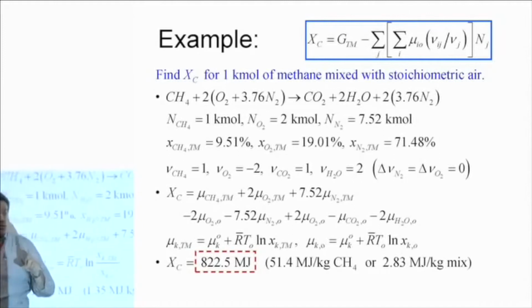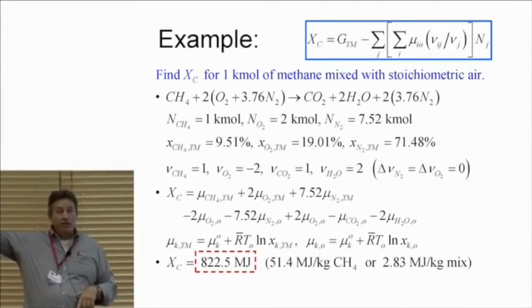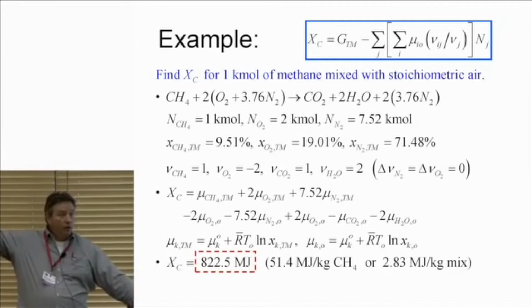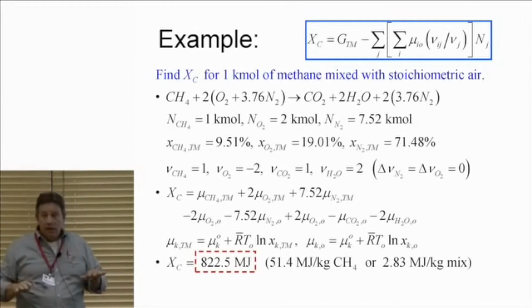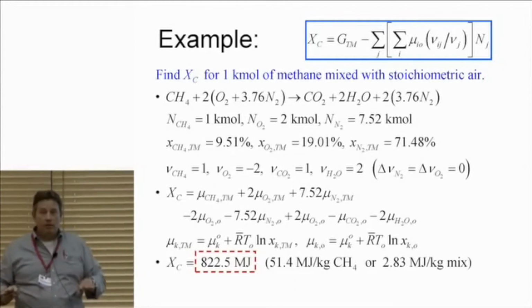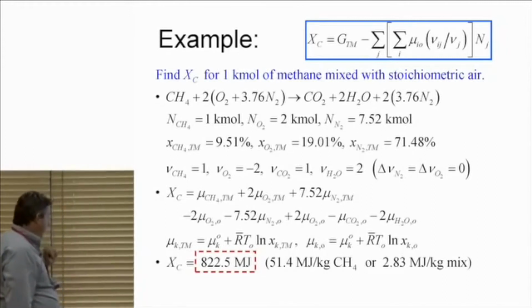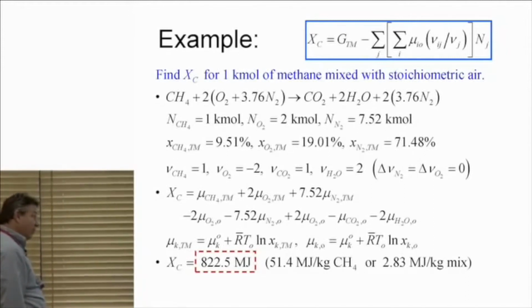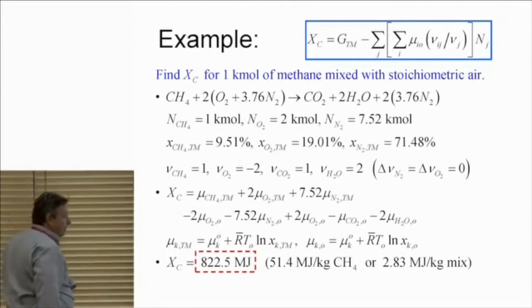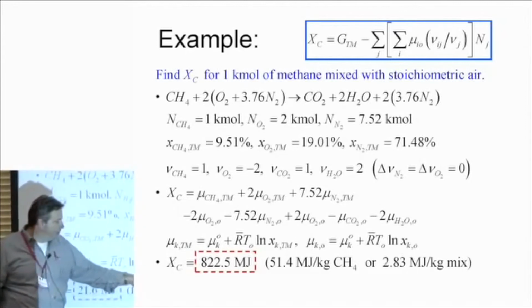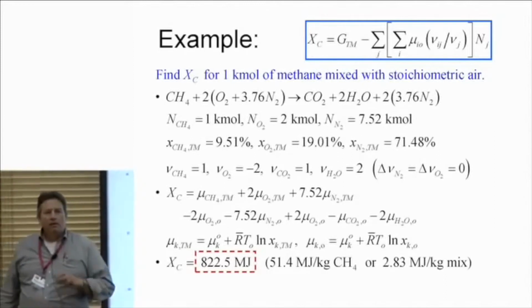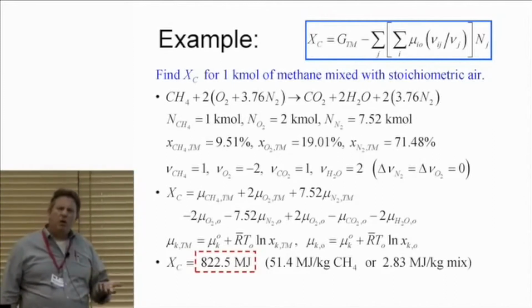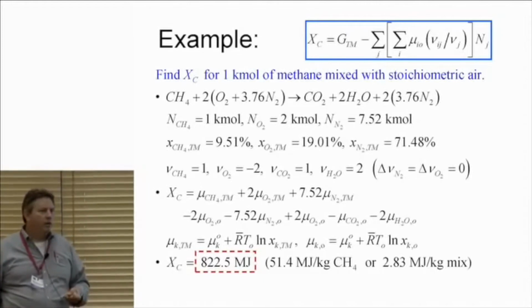Not the same chemical potentials, right? In one case the concentration is high, in the other case the concentration is low. This is the diffusive exergy that you were getting at before. Right? So I still have the ability to do work with exhaust, because exhaust is not at the composition of the environment. How much do I get? 21.6, it's getting small. Or if I try this differently, 1.35 megajoules per kilogram of methane, or 2.6% of the chemical exergy. So it's small, diffusive value. But hold that thought.